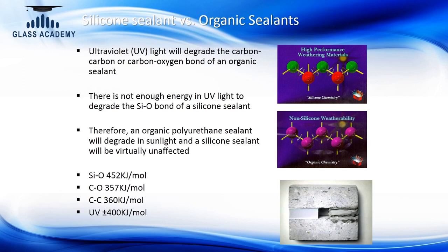That is the reason this chemistry has proven much more durable and long lasting than the other chemistries which came before silicone chemistry. So I want you to really understand this particular slide, because it gives you an overall view of why you should use a silicone sealant versus an organic sealant for external applications.